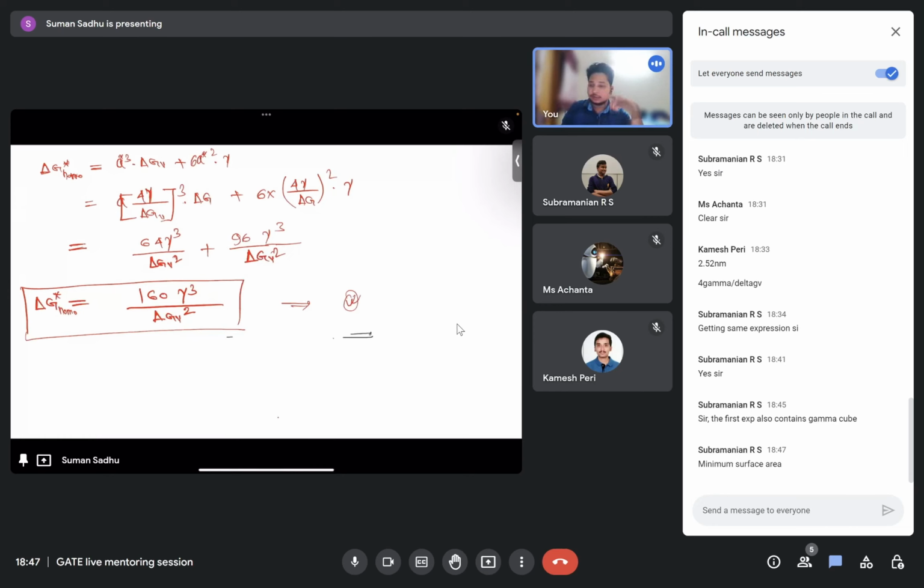But if you think in terms of crystallography, we have 14 Bravais lattices, right? If you combine any of those, it is not possible to form an exact spherical shape nucleus. So then what should be the nucleus shape which will give you the minimum surface area?